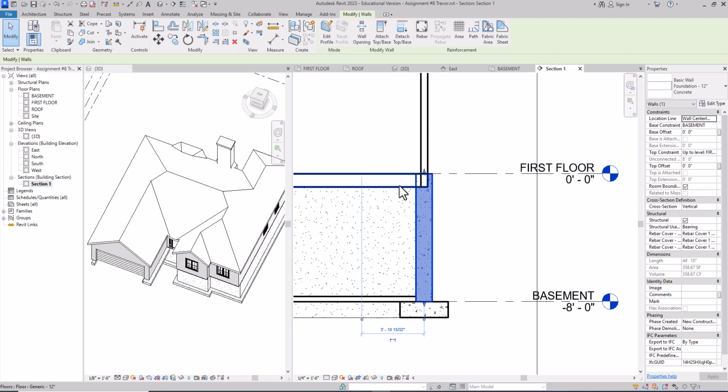Right now we're using a generic 12-inch, when really, if you think about it, there's a subfloor that's 3/4 of an inch, and there's a 2 by 10 potentially that's not really 10, but it's like 9 1/4. So the floor might be 10 inches. And then you also have a mud sill underneath that, which isn't really 2 by 6, it's actually 1.5.